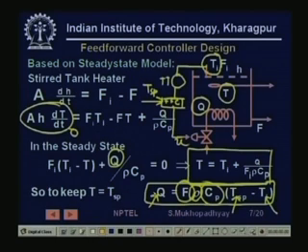So you see that if I make any error in, let us say, the value of rho, say the value of density of the liquid, then immediately the value of Q will be more and the temperature will not match T set point, right. So this is our problem. However, we have been able to design a feed forward controller based on a steady state model. So let us see some remarks about the controller.